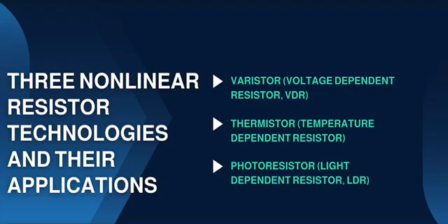And for the thermistor, it depends on the temperature, and it's used in temperature sensing and control as well. It can be found in thermostats and temperature sensors as well. And the idea behind it is that the resistance changes in a non-linear fashion as the temperature rises.